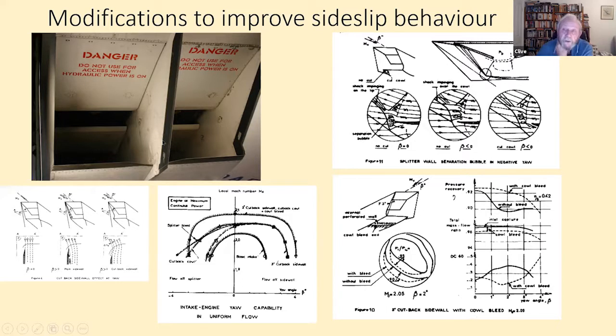The higher velocity means a higher Mach number, so that these shock waves on the splitter side would converge onto the cowl, and they would produce a sufficiently large adverse pressure gradient to generate some interesting flow conditions in that area.